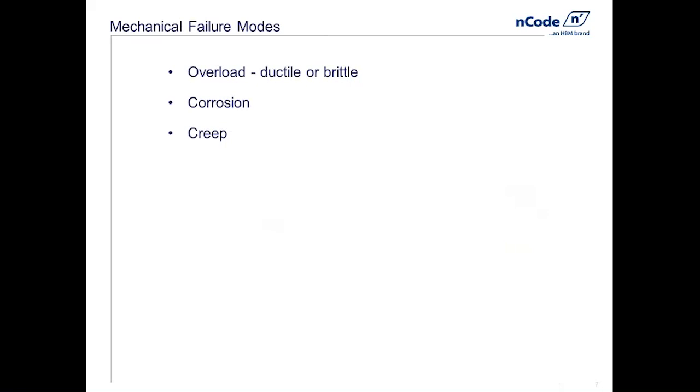Creep can also be a problem. And what I mean by creep is elevated temperature causing mobility of molecules. So another way to put that would be at high temperatures, materials can begin to behave like taffy, can begin to move in, to be technical, a viscoelastic or viscoplastic manner. In other words, time dependent, almost liquid-like. This happens in very high temperature applications with a number of metals. It can even happen at room temperature with, say, a particle board shelf that may be holding up a big old television at home. You may have a particle board shelf that you've noticed has slowly sagged. And that's because the glue that holds the particles of the particle board together is sufficiently weak, even at room temperature, to allow steady stress to cause time-dependent deformation.